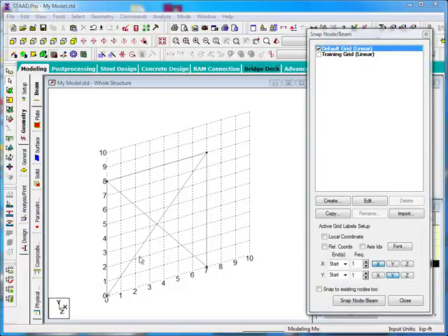Also recognize that there would be nothing that prevents us from setting up a 1 unit by 1 unit grid system that had a spacing of 8 feet in the vertical direction and 7 feet in the horizontal direction, so it was literally just one big square with only 4 intersections to potentially snap to. So the key there is to make sure that you use grid systems to their best advantage. Related to that topic is the way that grids in Staad.Pro behave. The entities that are placed using this default grid are not actually attached to that grid.